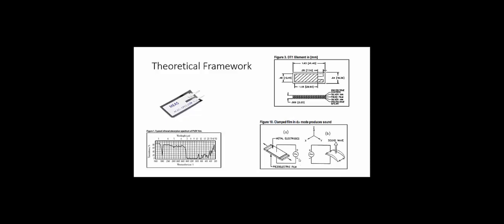For example, the voltage that comes out of the piezo element when it's bent is around 200 to 800 or 1000 millivolts. We are going to take that range to the comparator, and when the sensor reaches this voltage, it's going to produce a signal, that is some pulses.